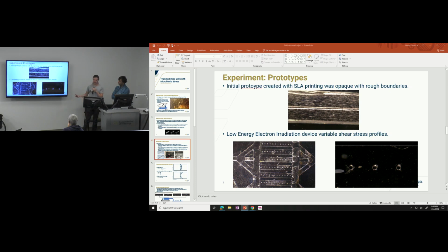But the reason why we used it here is it has very nice corners, but a very high shear stress regime. But it's very unpredictable, especially because there's a lot of supports in these channels to maintain a 100 micron thickness that these organisms have to deal with, these pillars. And around these pillars, it's very unpredictable what the shear stresses would be, especially on the start and stop of the pump.